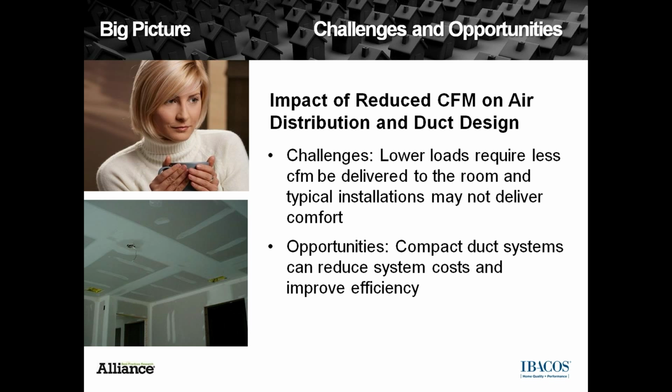Challenges and opportunities around these houses that have lower loads. A lower heating or cooling load means there's going to be less CFM required to meet that load. Our traditional way of delivering that air to the room may not deliver the comfort we're looking for. The opportunity of these lower loads and lower CFM delivered is that we can have smaller, more compact duct systems, with fewer diffusers or outlets in the room, and still get the efficiency that we're looking for.